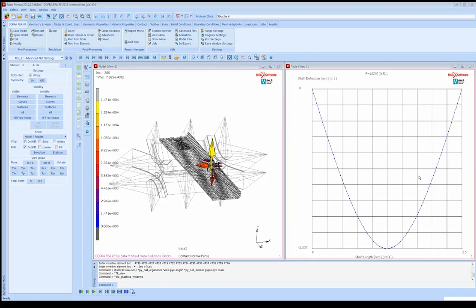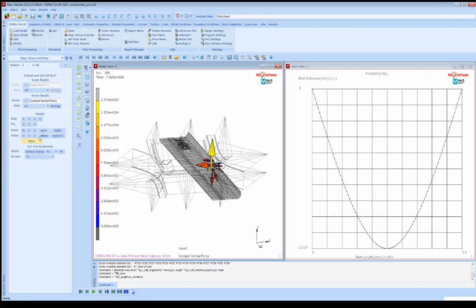So what are the typical outputs we go through during the post-processing? Well, for myself, and it's a question I'm asked quite often, as a minimum, I would certainly look at displacements in the beginning in the X and Y direction. But for myself, I actually find the most from strain in the Z direction, looking for elongation.